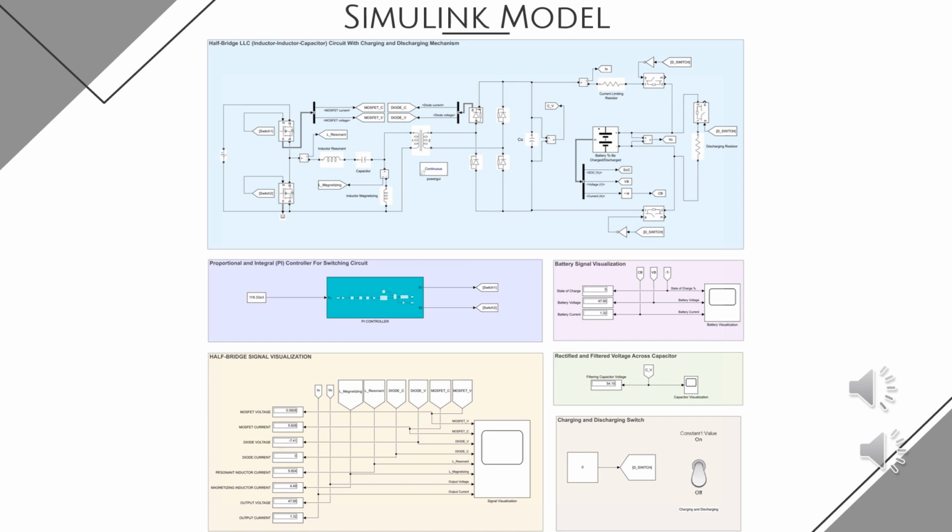So here we have the entire Simulink model. On the very top you can see the main circuit, which I will go into more detail in the next slide. You can also see the PI controller, and the display monitors in which we can see the real values in real time of all the MOSFETs and diodes and everything. On the very right we have the switch which we can turn on and off to charge and discharge the battery, and the battery will discharge because of the discharging resistor.